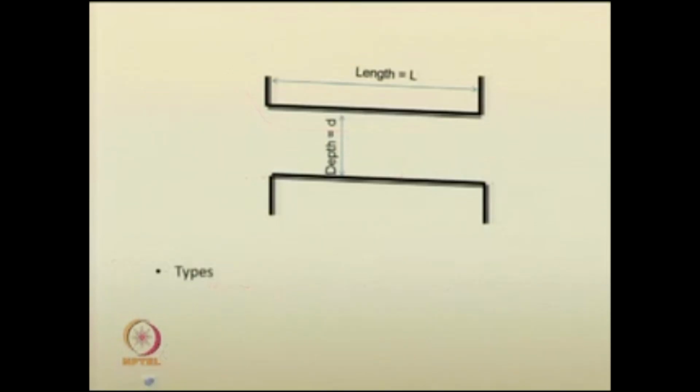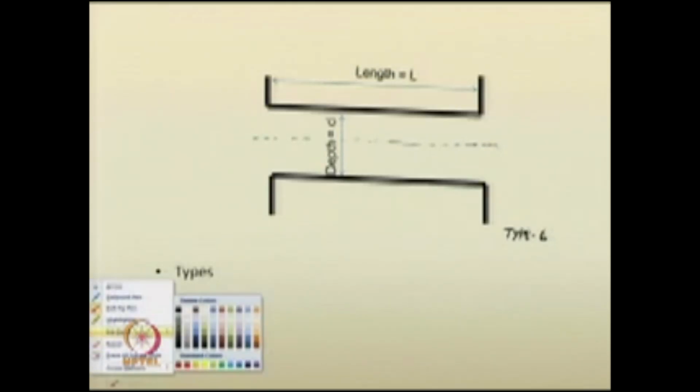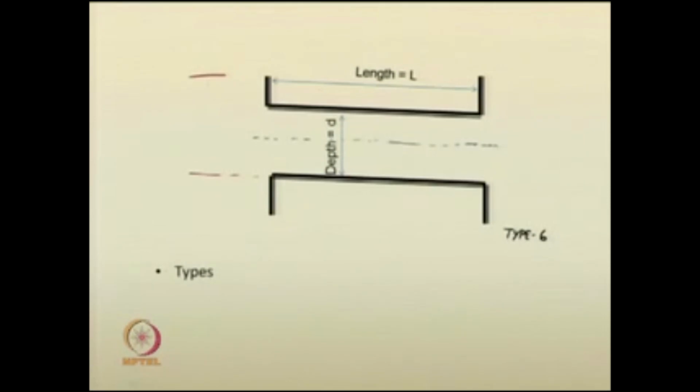The flow inside the culvert is also subcritical. Next, the type 6 flow you can discuss. Let me draw the critical flow depth inside this, and if this is the headwater depth H, we are suggesting H less than H star, and the flow goes all of a sudden into the supercritical form.